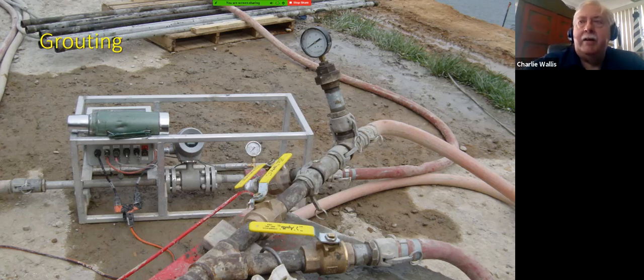We also encounter cases where a permeable material like gravel or stone is put underneath of a riser base, and that's not desirable and that's not allowed. And in these types of situations, they need to grout the voids between the gravel particles to make it almost act as if it's concrete and to make it less permeable. And grout is simply water and sand that's mixed together, and then it's injected under pressure.